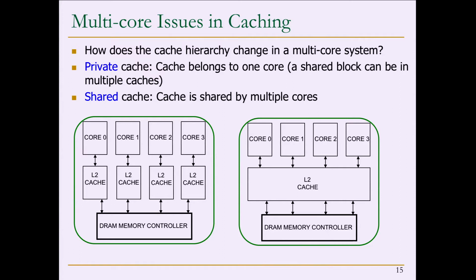Here on the chip, you have a choice. You have this L2 cache. Is it private or is it shared? Why am I not depicting the L1 cache? Well, L1 cache is very closely tied to the processor itself. So you can also make that shared, but everything we've discussed so far says L1 cache is very tightly coupled to the pipeline, and the design decisions of the L1 caches are made mainly by the pipeline frequency, for example. So even L1 caches may be shared between different threads over here, but let's ignore that for now.